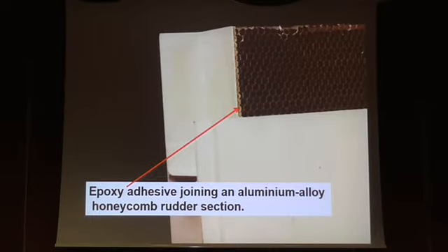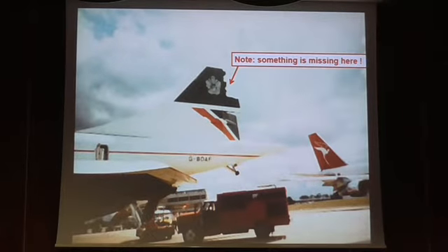So it's all glued. These days, of course, it's more likely to be carbon fibre skins and a Nomex, that's impregnated paper with phenolic honeycomb. But there are problems from time to time. This is a rather famous aircraft, now retired. You probably recognise the Concorde, and it had 2 or 3 failures like this.